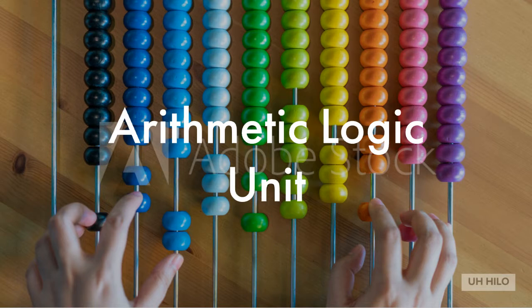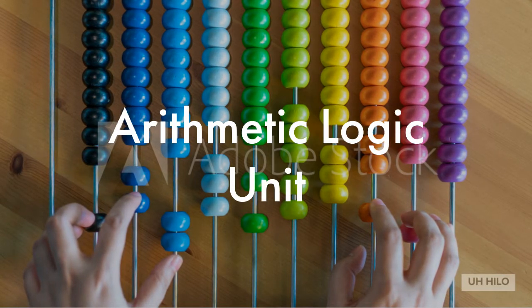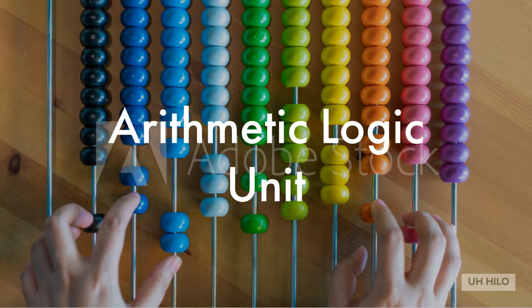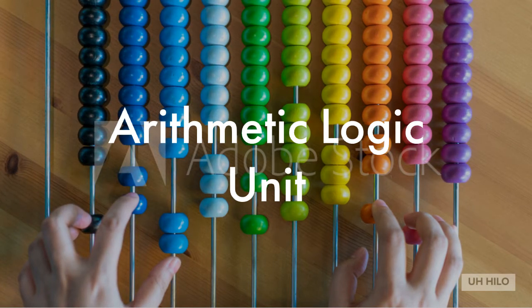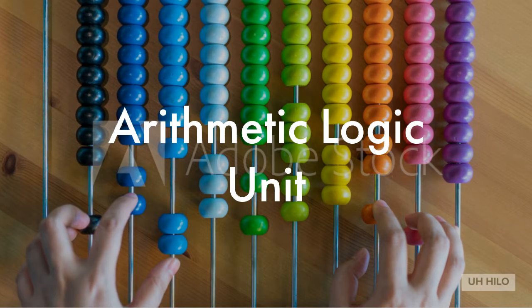The arithmetic logic unit, or ALU, is the brains behind the operation. It has separate high-speed access registers for storage of operands. ALU operations are add, subtract, multiply, divide, and compare. We have circuits for each operation, so all the operations get done. We then select the result we want using our friend the multiplexer.